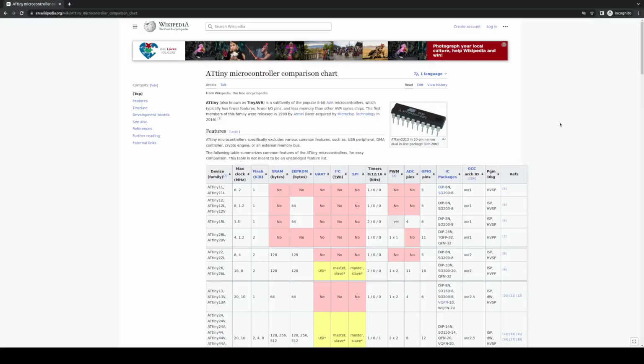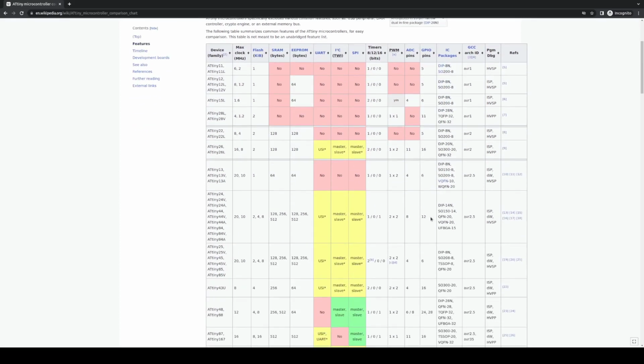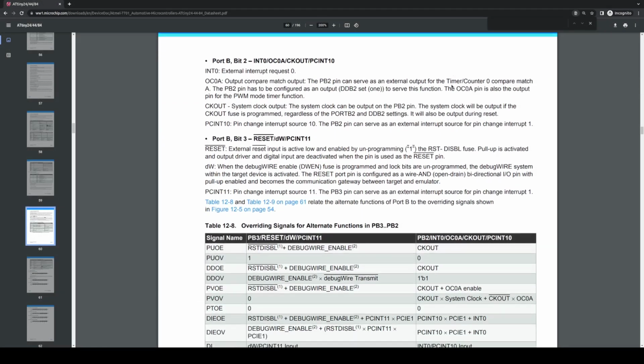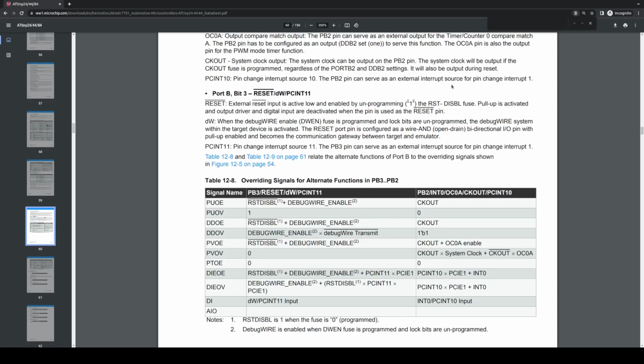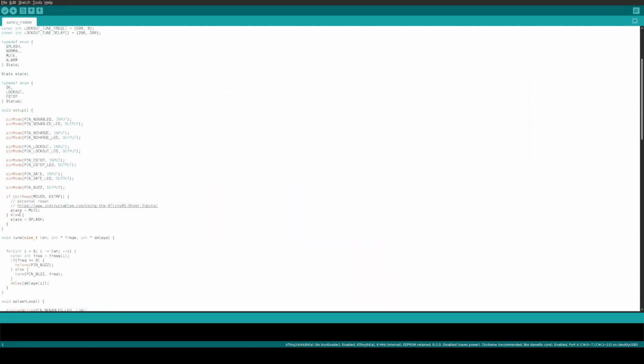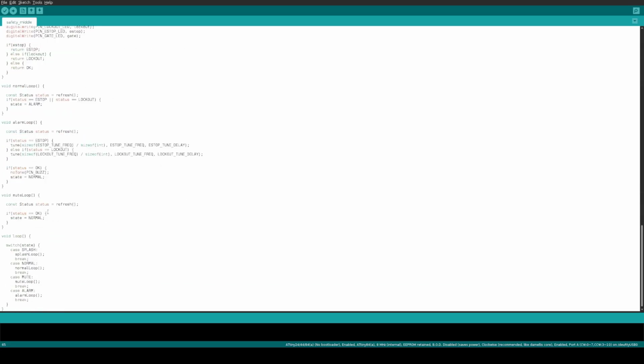Maybe not. One little trick I used here: I was right at the number of I/O pins for an ATtiny84. I did consider low-level programming to turn the reset pin into a normal input, although that makes reprogramming a little bit more involved. And then I realised I could just use the reset functionality as the mute function. So during setup, we check to see if we were reset, and if so, skip the splash sequence and ignore any current lockout or e-stop state. Once those states clear though, they can trigger the buzzer again.